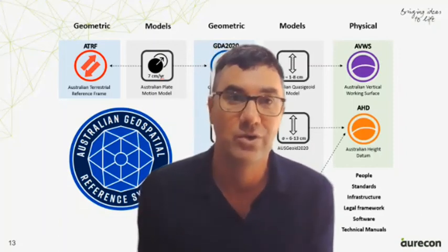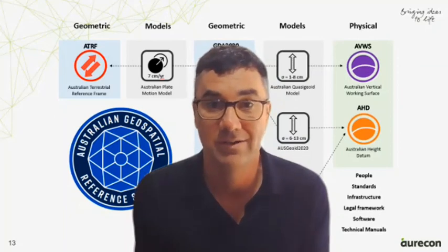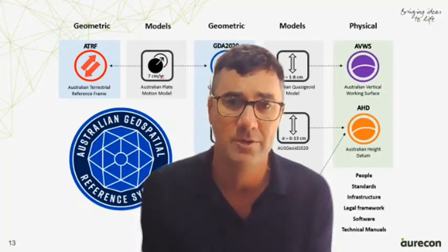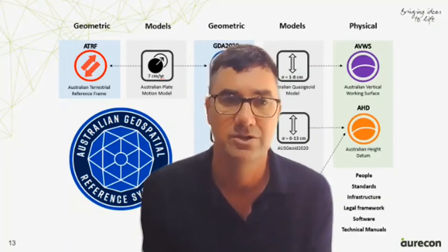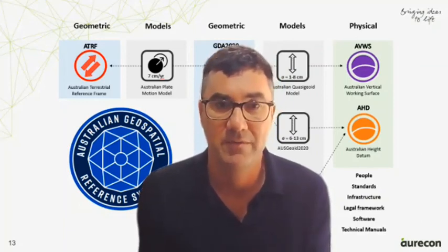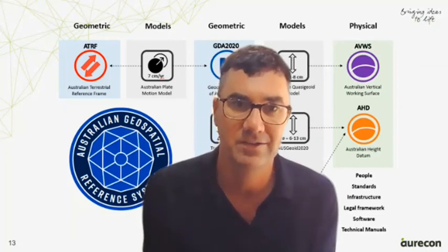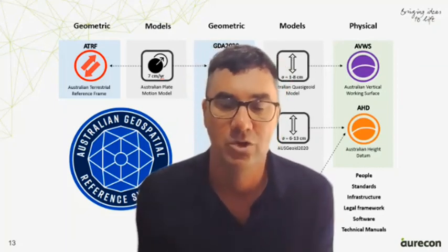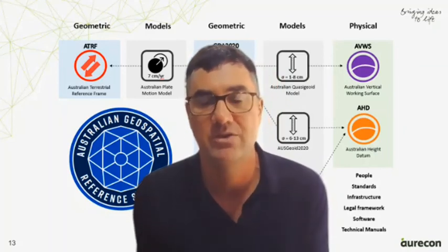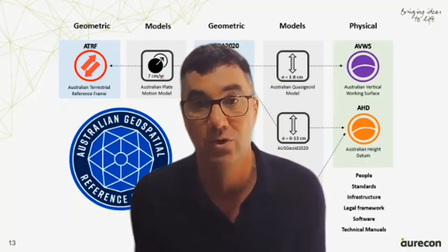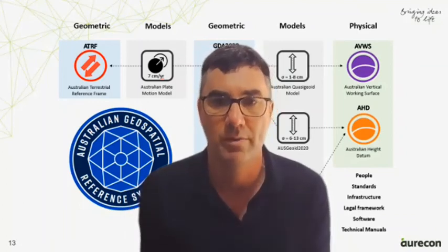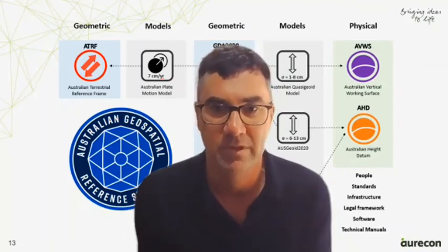Now, it's not mandatory for any of our clients or for us to move to GDA 2020. It's a choice that our clients will make when the time is right for them, and they might not move to GDA 2020. But if they do take old data sets through, there's no right or wrong, it's just a different way of expressing the coordinates in the data that they possess. But if they do move data from 94 or even an older datum to GDA 2020, we have robust tools to help us do that.